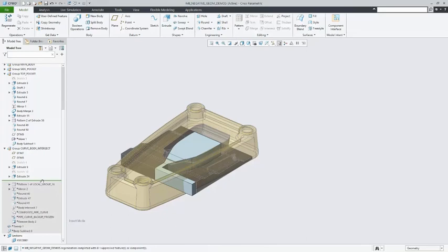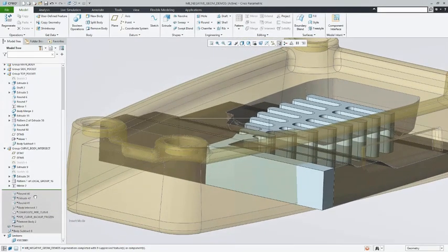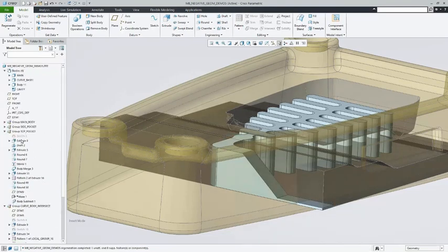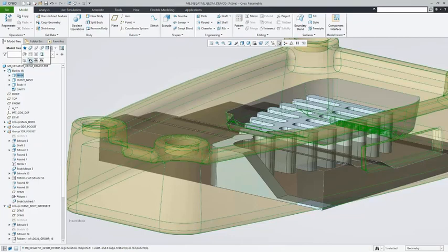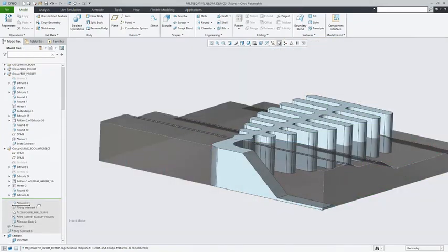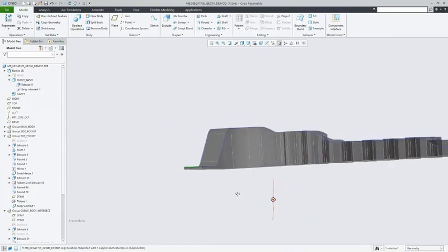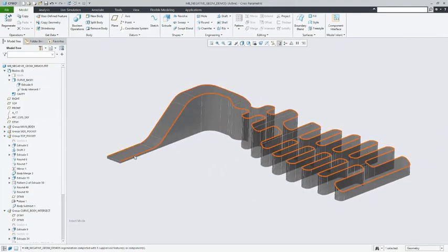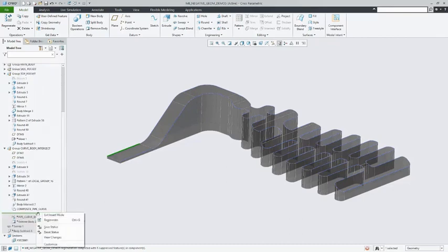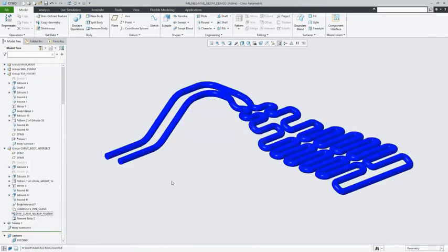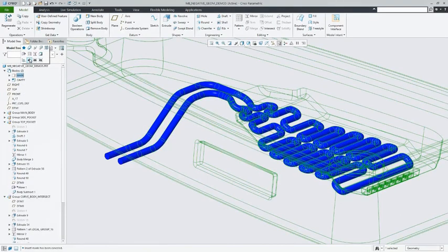So the multi-body concept allows us to do that with the regular solid modeling tools in an intuitive and very familiar way, eliminating the need to switch to surface and quilt based tools and workflows for these situations. And finally, the intersection of these two bodies now allows us to use the intersection edges as the guiding curve for our sweep. After we derive that curve, we can of course get rid of these two tool bodies, helper bodies that we used to construct this geometry.